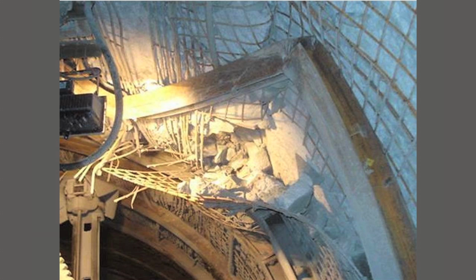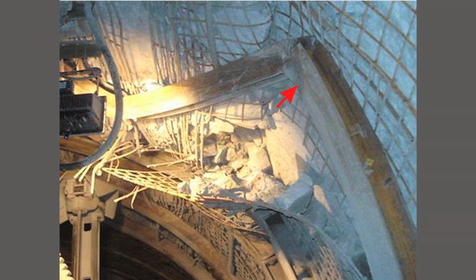But the important thing about this is that the steel sets are deformable. So in spite of the fact that this one in the foreground is bent right out of shape, it still has capacity to keep the damaged rock back. And because they had high-speed transportation, they could bring their crews in almost immediately and start cleaning up, and they simply remove the damaged sets, replace them, and open the ground up.